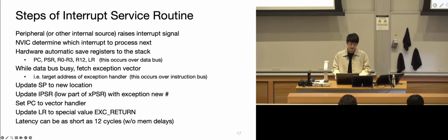And the address will be fetched to the core and then executed, just like we showed before. I think one classmate just mentioned, when we have multiple interrupts happening or triggering, what happens is that they're going to be executed by priority, and the smaller number means higher priority.